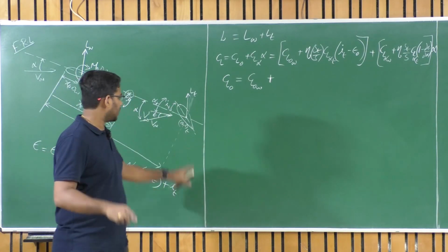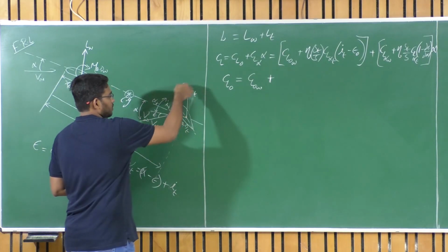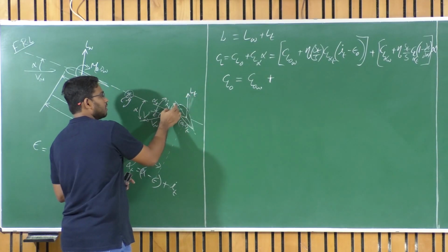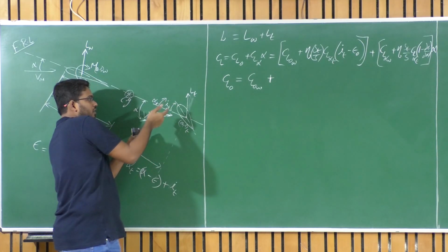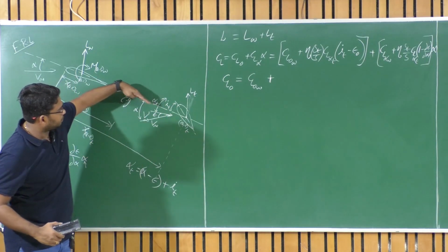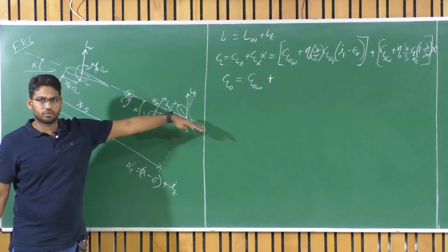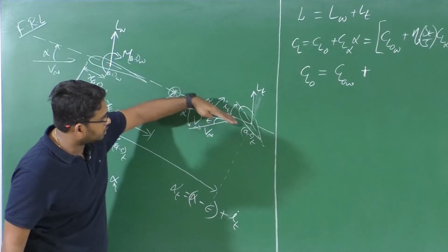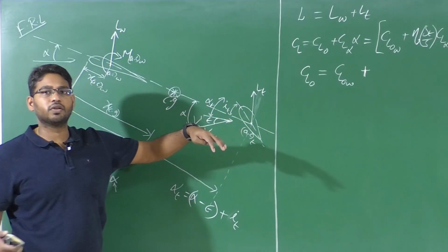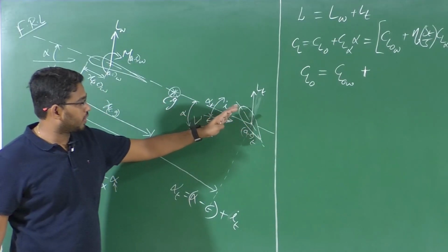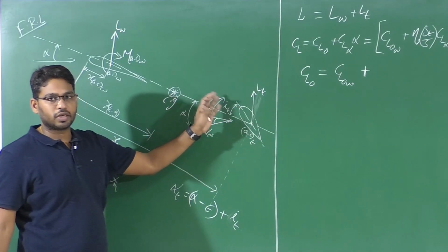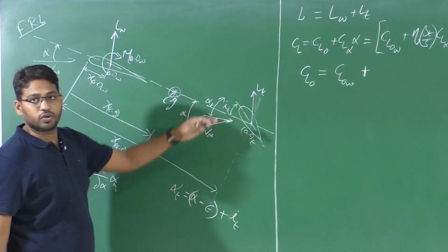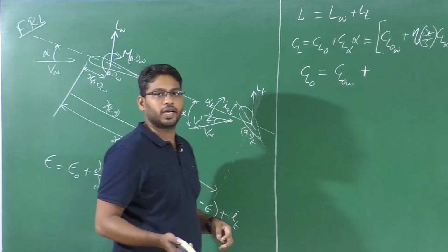That means such an amount of lift coefficient, CL alpha times the angle of attack, which is nothing but, at zero angle of attack, V infinity prime is aligned along with this flow, isn't it? Let us assume there is no epsilon. V infinity is aligned with the fuselage reference line. Effectively, there is no angle of attack. Since we have given a tail setting, which is i of t, the aircraft will continuously experience some lift because of the tail, right? Even at zero angle of attack.